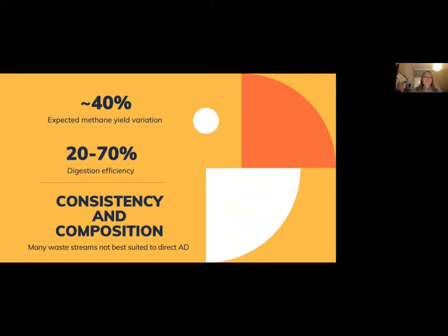And when you think of a raw waste, it's not often going to be consistent in its composition or characteristics, though it will be from certain defined industrial processes. So often high rate anaerobic digestion does well in these conditions. But many waste streams, such as those with high salt or high sulfide concentrations, are deemed unsuitable or unfavorable for treatment. And yet often when we perform trials in the lab, the outcomes are much more favorable.